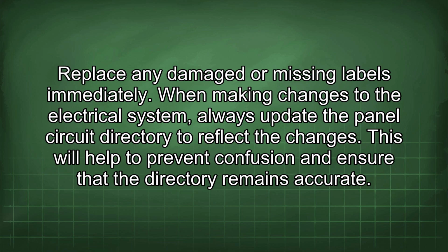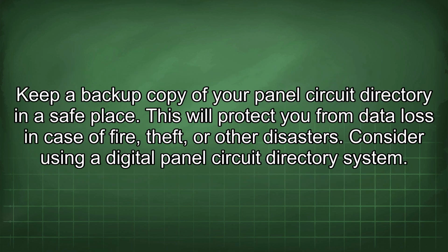When making changes to the electrical system, always update the panel circuit directory to reflect the changes. This will help to prevent confusion and ensure that the directory remains accurate. Keep a backup copy of your panel circuit directory in a safe place. This will protect you from data loss in case of fire, theft, or other disasters.